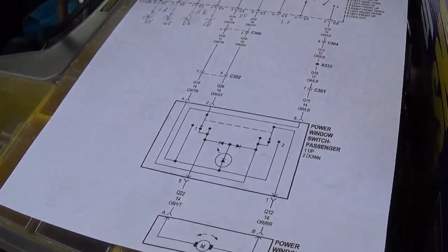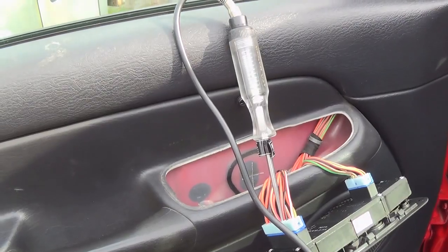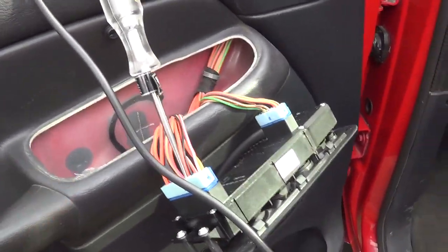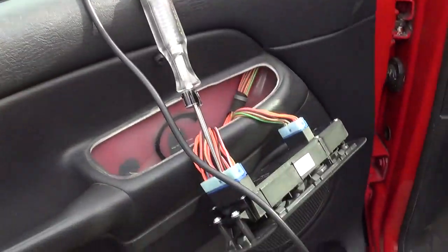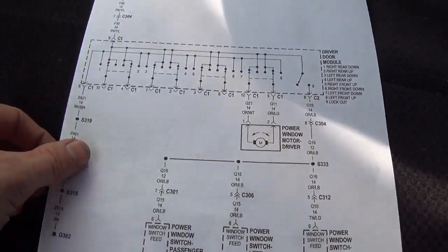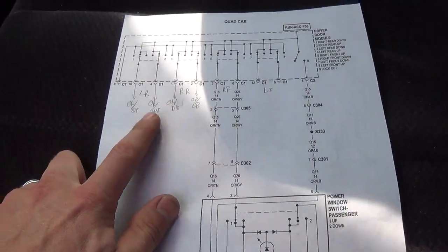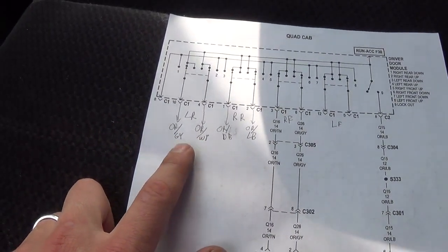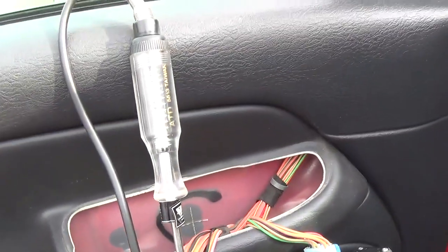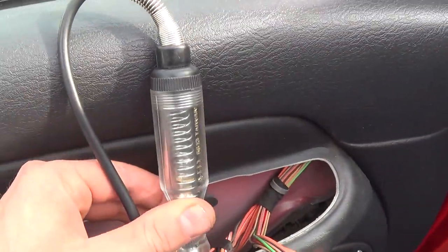So let's do some poking around with a test light and see if this thing is getting any power at all. We don't want to get hung up on why those 2 wires for the driver's window didn't have constant power here according to our diagram. Let's move on to our problem window, which is the left rear. Orange and white and orange and gray, those 2 wires, and we'll flip the switch here and see if our test light responds. So I'm on the orange and gray now. Okay, so that's in there.